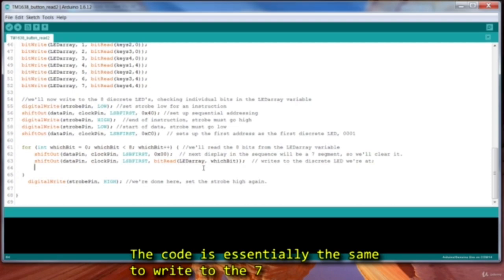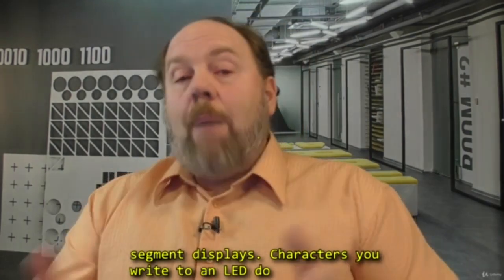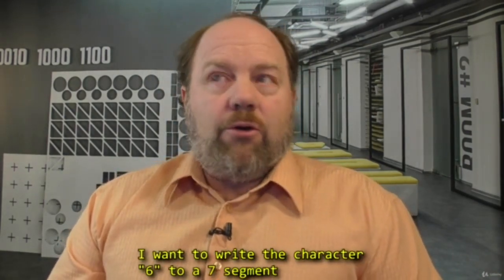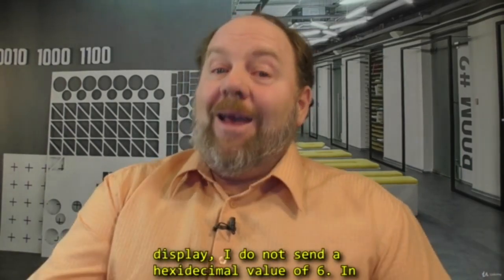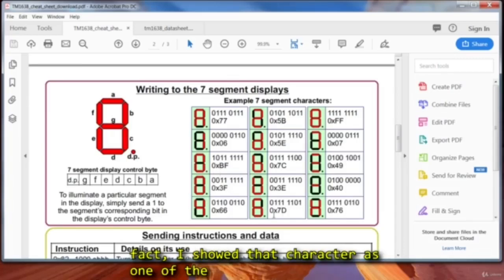The code is essentially the same to write to the 7-segment displays. Characters you write to an LED do not match their hexadecimal values. For example, if I want to write the character 6 to a 7-segment display, I do not send a hexadecimal value of 6. In fact, I showed that character as one of the examples on the cheat sheet, page 2. To display a 6, I would send a hexadecimal 7D.